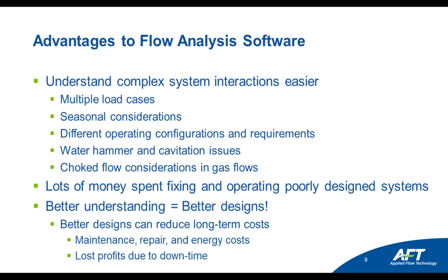There are several advantages to using flow analysis software, and really it just helps you understand your system and how things are interacting a lot better, especially when you have multiple load cases. If you're trying to see how things are operating in different seasons or different configurations and requirements, when you have various flow paths that are on at certain times and some that aren't, you might have water hammer or cavitation issues.